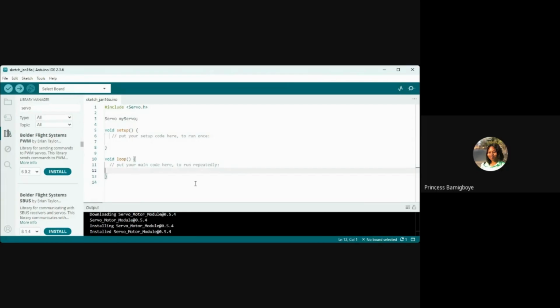Or unless you write a command that tells it that only when this happens, that's when that should happen. Otherwise, let nothing happen. But that's for if statements, else statements, if else statements, which I'll go deeper into later. Essentially, void loop is the part of the code that you want to run repeatedly. Void setup is the calibration of the code. I've started my generator, that's void setup. The generator is now continuously supplying electricity to the house after I've done the changeover. That is my void loop until I say otherwise.